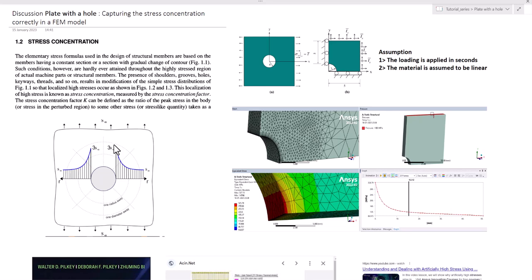Now, even after plotting the unaveraged stress, if you see the gradients jumping from one element to another, or even within one element there is a drastic difference in the stress values, then you can use the meshing control feature to refine the mesh in the local vicinity where the gradients are happening.